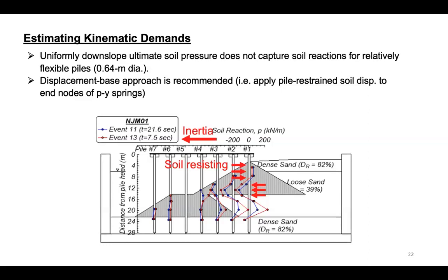So if you choose to use a force-based approach for these cases, you will be massively overestimating the lateral spreading force. This is particularly the case when you're dealing with relatively flexible piles, where the pile kind of follows the soil deformation pattern. For these cases, our recommended approach is to use a displacement-based approach, where, if you're using LPile, you would apply the soil displacements to the end node of the p-y springs, and you capture a more realistic behavior, more realistic soil reaction on your piles.